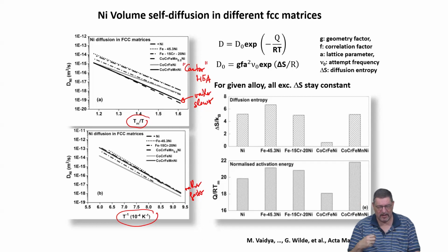Not so much that there is a new element and you change the configurational entropy, but that it's the specific choice of manganese and its interaction with the other binding partners, but also affecting how the other pairwise interactions, let's say between cobalt and chromium, are affected by adding or not adding manganese. So this is a very complex process affecting the whole alloy structure and all the interactions.